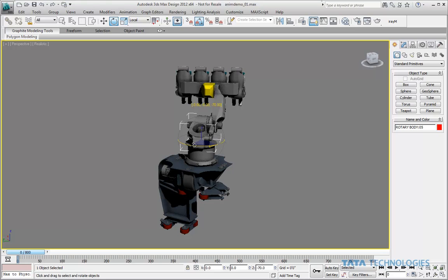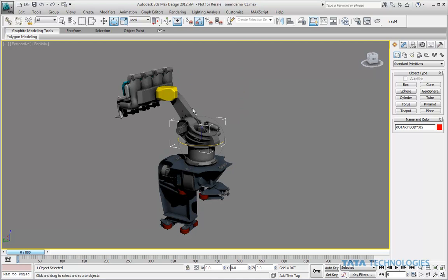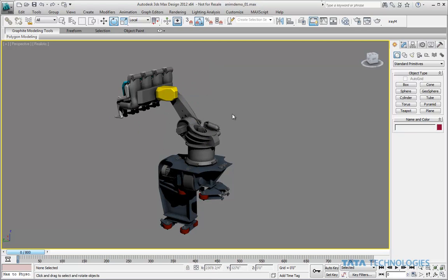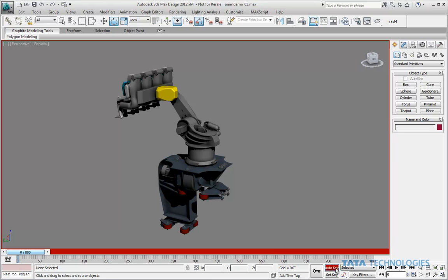Once that's been done, if we use something like our rotate command, you can see all of the child components in that kinematic chain follow along and adhere to that same motion. Now if I double click on the first element in the kinematic chain, sometimes it's useful to create a selection set, a saved selection set. I just call it RoboArm, because later on when we start making a keyframe animation, it'll be easier if we set that as the default selection. So we'll just pick the RoboArm as our default selection whenever we're making keyframe elements or setting our keyframes.